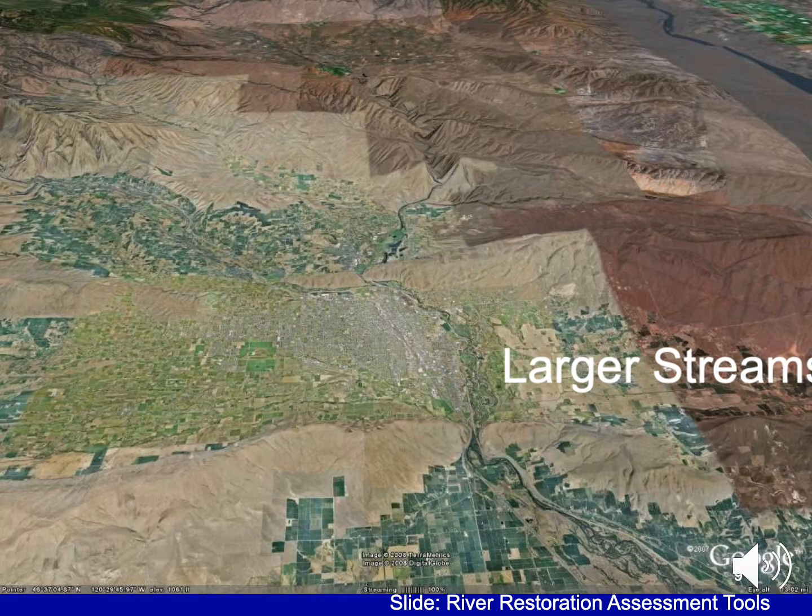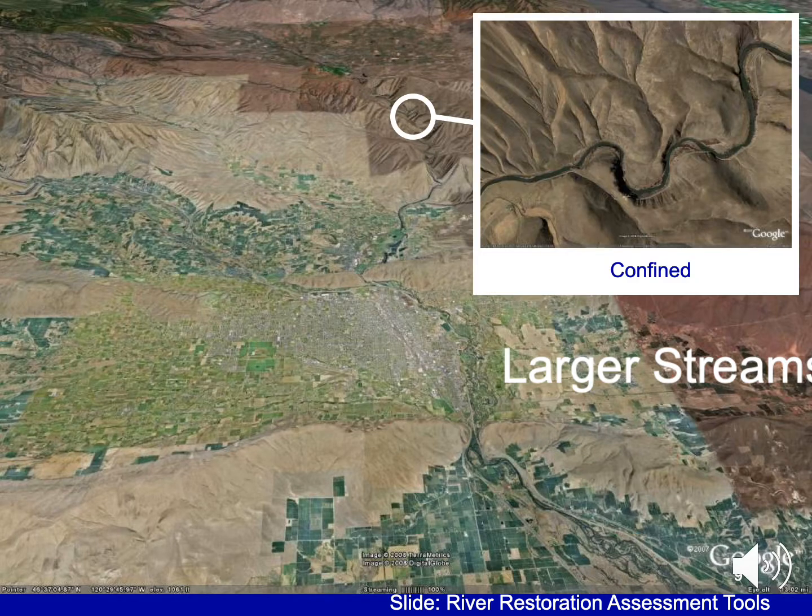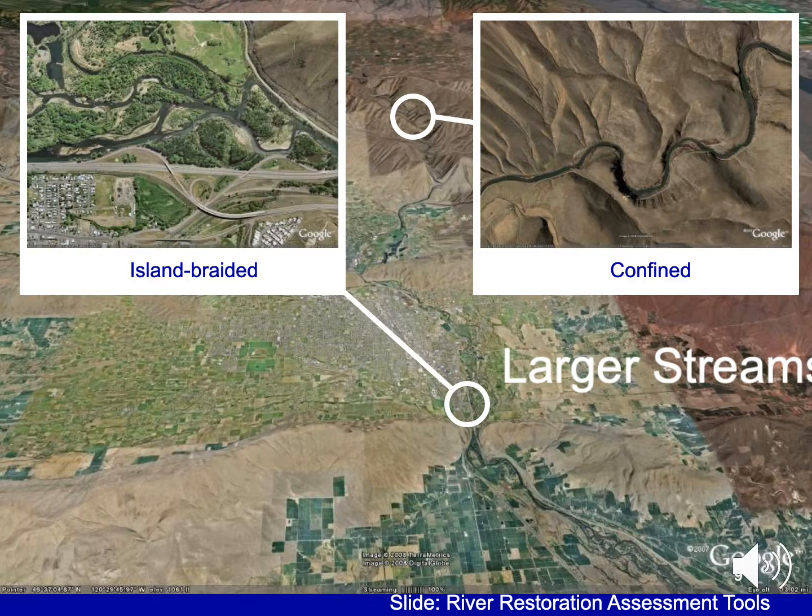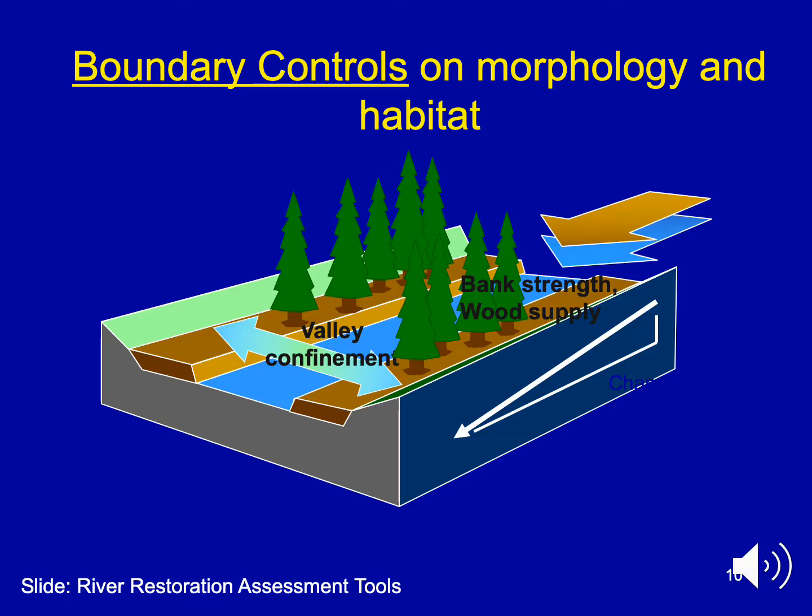Looking at larger streams, for folks up here, particularly we are talking now about Sacramento River scale systems. Up to now, I've kind of been talking about where your shear stress, your tractive forces, your sediment flux, your hydrologic flux come from. Those are your erosional forces. When you're looking at a river system, there's also your boundary controls, which is basically your resistive force, what's providing your resistive force to combine to produce your channel morphology.